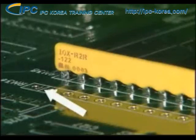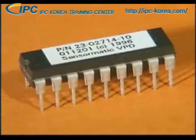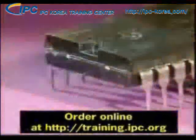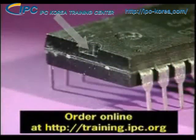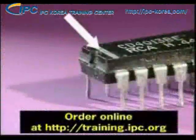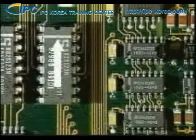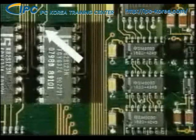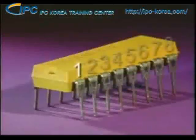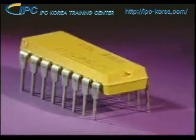The board usually has a square pad or a symbol or screened outline of the component shape to show correct orientation. IC manufacturers use a variety of methods to identify pin 1 on the component package. Markings may include a notch, a dimple, a wedge, a different edge or corner shape, a stripe, or the actual number. When viewed from the top, if the mark is on the top of the component, pin 1 is always to the left of the mark. The numbering on the other pins always proceeds in a counterclockwise direction around the component.